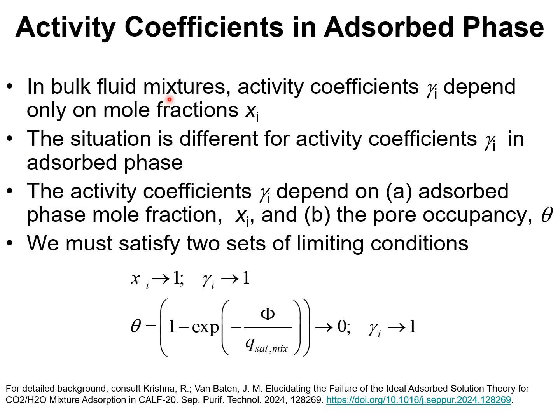In bulk fluid mixtures, the activity coefficients depend on the mixture compositions, say mole fractions x_i. The situation is different for activity coefficients in the adsorbed phase within microporous materials. In this case, the activity coefficients of any component i depend not only on the adsorbed phase mole fraction x_i, but also on the pore occupancy.